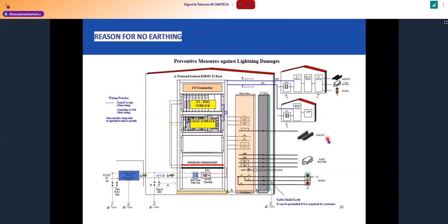all our communications are optical communications. So we don't need any other converter or any other information to be converted. If all are OFC, then there is no possibility of lightning coming into the OFC. That is one of the points. This is the fourth point, and the fifth point is in-house isolation. For example, from the ground, we will be providing rubber beading here, so nothing can come from the ground, from the floor. This is the fifth one.